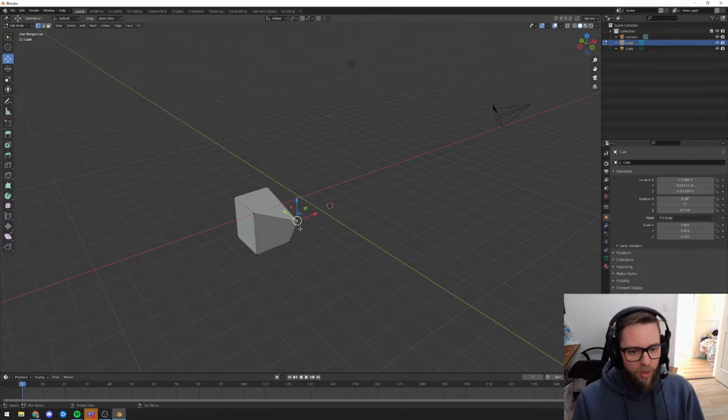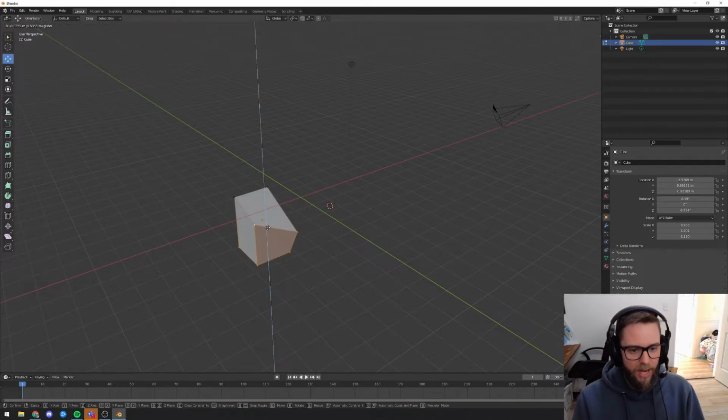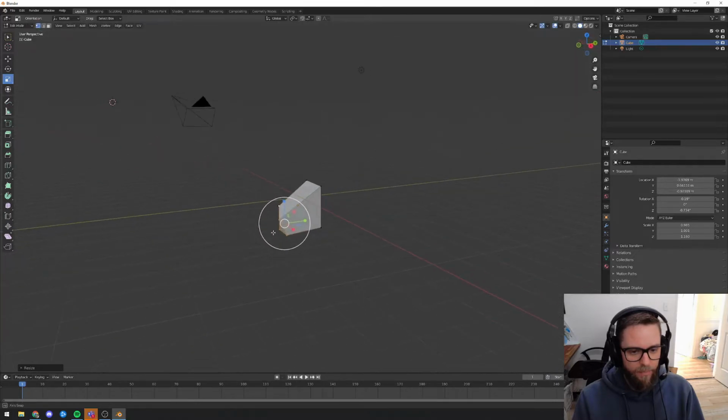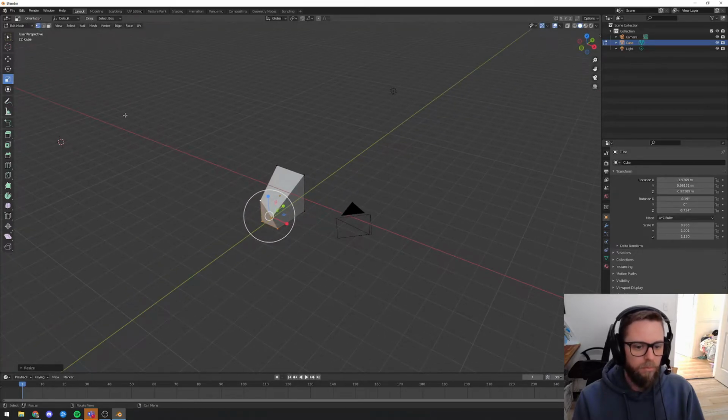Now to choose more than one vertex, you could hold shift and select another one, or you could, for example, press C on the keyboard to bring up this selection circle, and then everything that I click and scribble over will get selected. Hit escape to get out of that circle select, and then I could start editing all of those vertices that I've just selected, like this. The next one here, I'm going to double press A to unselect everything.